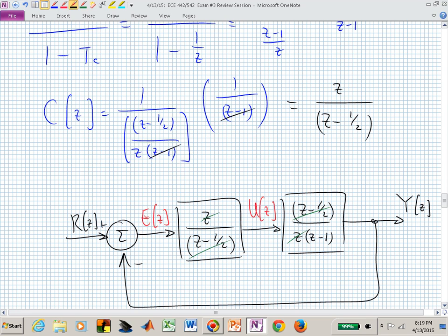So now replace this leftmost block with 1, disconnect the feedback. That's now saying K is equal to 0. We don't have any feedback, and you just have an open loop system. Your poles are in the open loop location. But as soon as you bump that K up a little bit, you've introduced feedback, you've now adjusted the K, and you're back in your warm and fuzzy environment. If that doesn't help, don't worry too much about that explanation at this point. Okay?